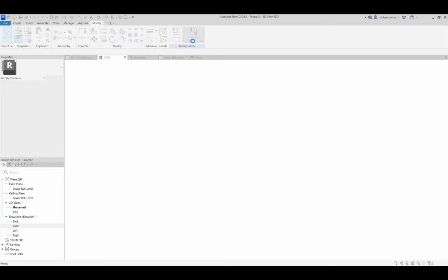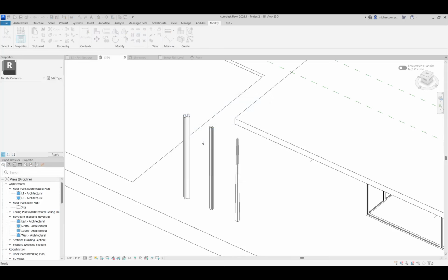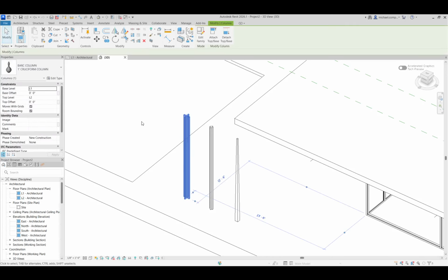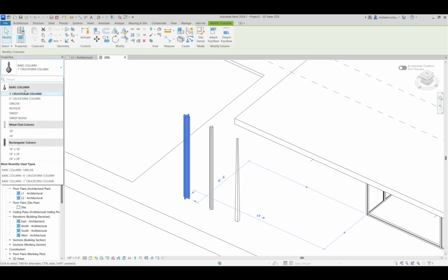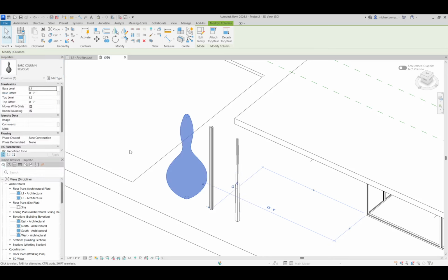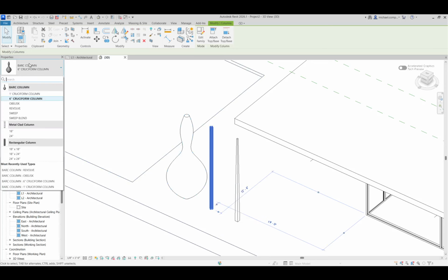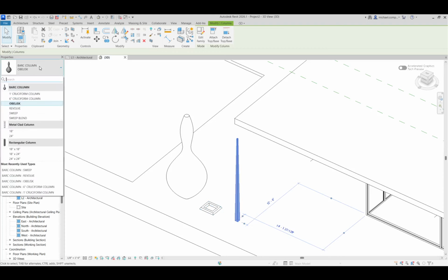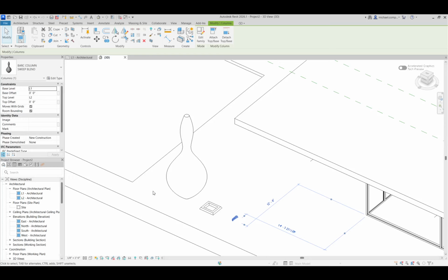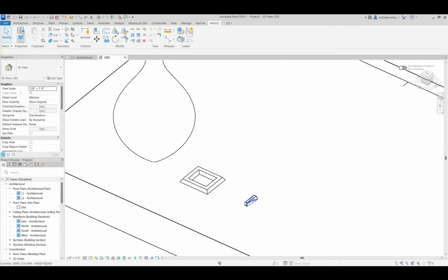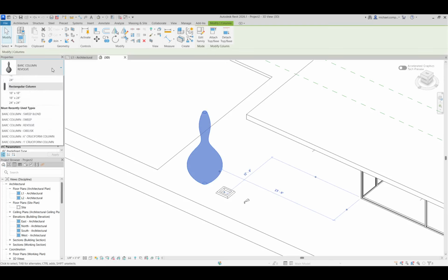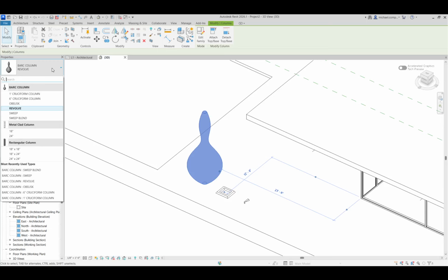We're going to loop that back into the model. Now I'm not going to make new ones. I'm just going to flex these, right? So here's the 1 foot cruciform. I actually want that to be the revolve, and there it is. I want that one to be the sweep, and there it is. I want that one to be the sweep blend, and there it is, right? So that is how you use a parametric family in freeform modeling, a parametric family that is driven by a yes-no command.